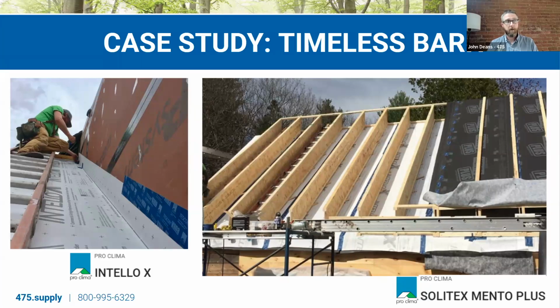And then of course you're going to bury it in insulation, and it's going to be your airtight layer and your smart vapor control for the insulation assembly. It's going to help keep moisture from migrating from the inside of the building into the roof assembly to begin with. And in this case, we put it down over the walls to connect with our sheathing, which was going to be our air barrier, which we'll see in a second. So the assembly here is that IntelliX, that's all taped.